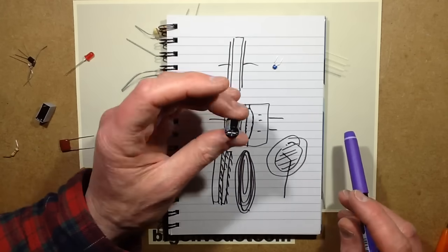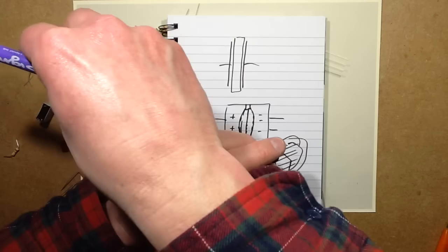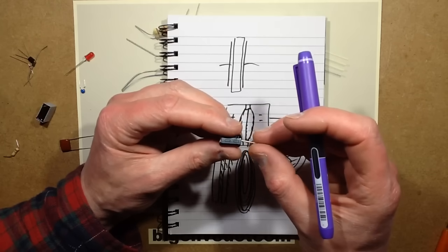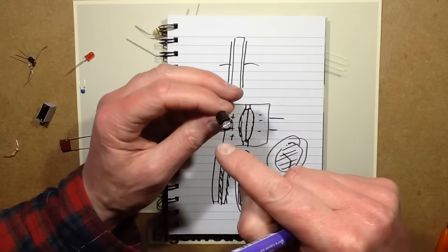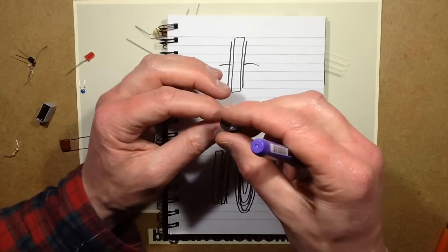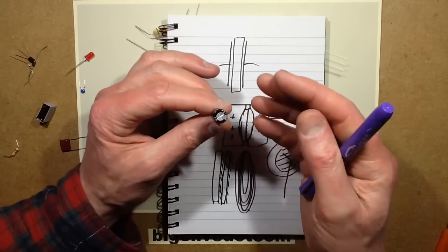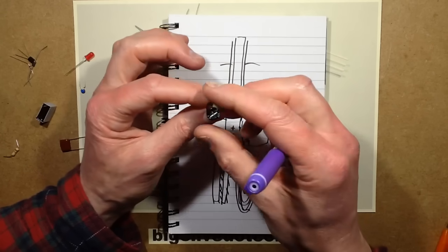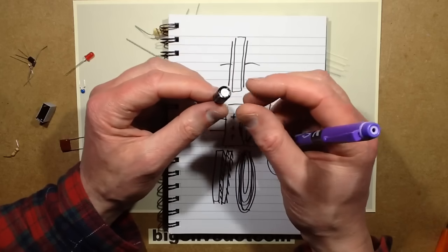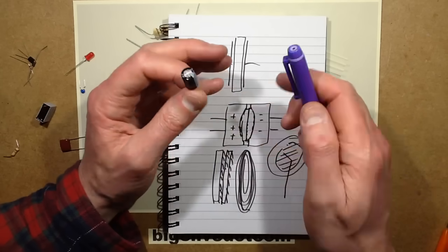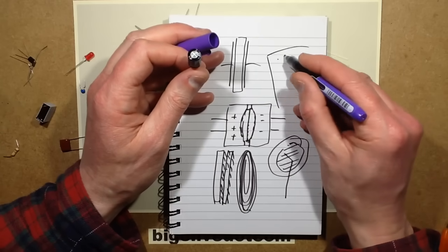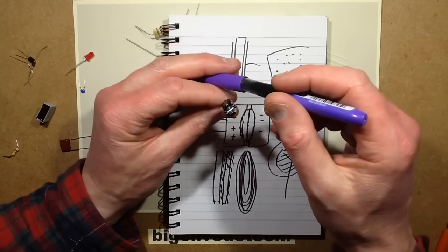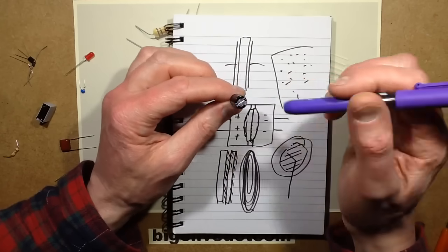So, electrolytic capacitors are one of the more exciting capacitors, and I don't mean that in a good way. The electrolytic capacitors, to achieve such a high capacitance, they contain a liquid electrolyte. And they have a very thin foil inside. And the foil, to create an extremely thin insulator, they form an oxide layer on the aluminium foil in there. And that means it really is like micron thick, which means that they can get a very high capacitance in a small area. But to couple onto that surface, they have to use a liquid electrolyte, because if you looked at the foil, it would look all pitted and mottled with that oxide coating. So to get a good coupling, they use a liquid that just fills in those gaps. And that's one of the downsides of, well, it's many of the downsides of the electrolytic capacitor.